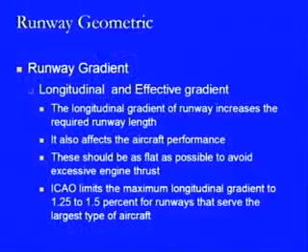So therefore, we are taking these two things together here, and what we found is that the longitudinal gradient of a runway increases the required runway length. That is the one thing. If it is flat and it is a zero gradient condition, then there is no change in the length of the runway strip. But as soon as there is a longitudinal gradient, then the length of the runway strip will change. It also affects the aircraft performance in the sense that if a number of gradients are provided,